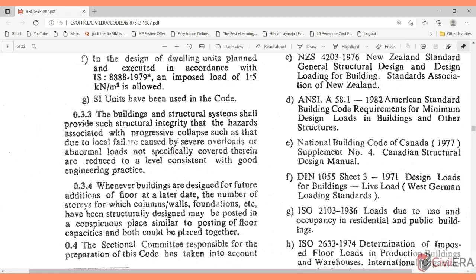No, that's not the clause meaning. It's in fact making you responsible for progressive collapse. So what it means is that your scheme should be really good so that you have an alternate load path in your building, and because of a robust scheme, your normal detailing or good engineering practice is going to bridge any failure of a key member, and that will allow an alternate load path, and your building is not going to completely collapse.